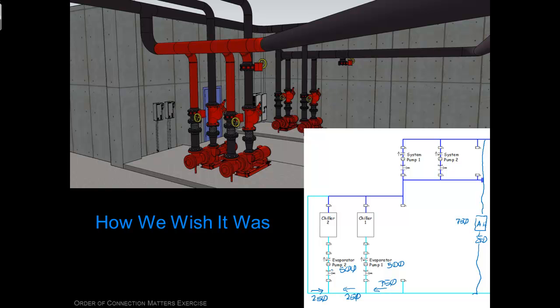But now, instead of both chillers seeing that recirculated water, only this chiller sees recirculated water. Its entering water temperature tends to drop, which means it unloads, and this is the chiller with the variable frequency drive. So it unloads and does its thing while this chiller remains at full load. Purely by virtue of this one piping connection is how that's made to happen.